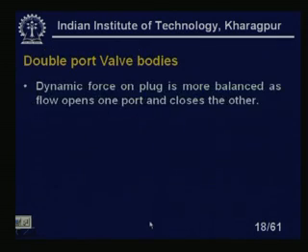Double port valve bodies: we have already seen the double port valve in lesson 38, so we will now look at the details. Dynamic force on the plug is more balanced as flow opens one port and closes the other. So there are two valves, and obviously if liquid flows in one port, in the other port the liquid will stop.